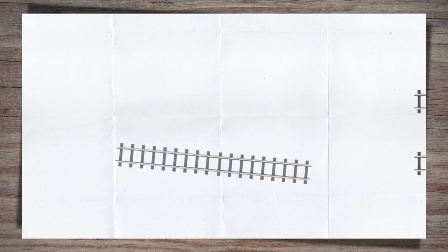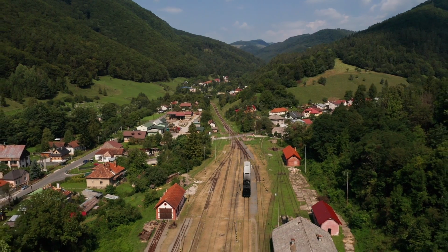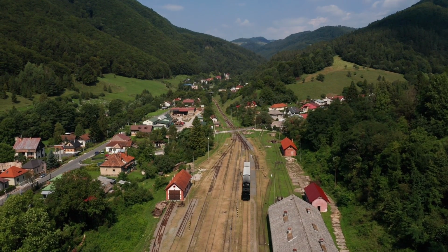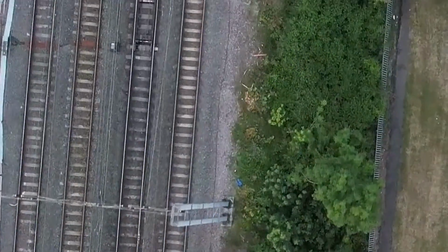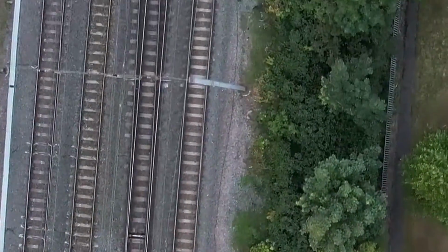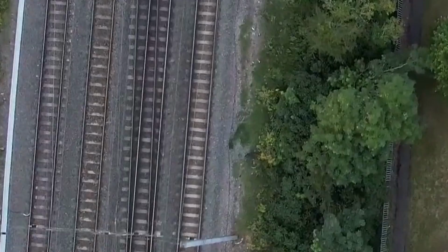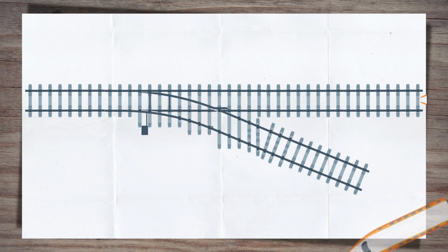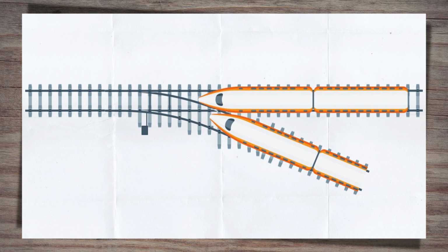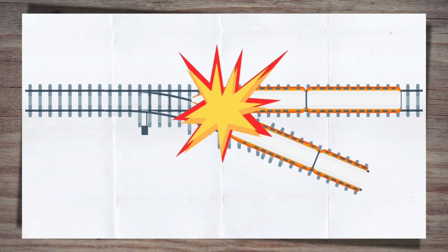There is one area that the track interval, or distance between the tracks, is intentionally reduced. This is around switches or points. Switches or points are the parts of the track where trains can change tracks. This means that two tracks come together, reducing the distance eventually down to zero, along with the passing clearance. As these two tracks get closer together, there is a chance of a train sustaining a glancing blow or a full-on collision with another. So, how are trains kept safe around junctions?